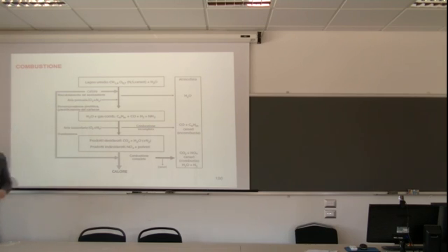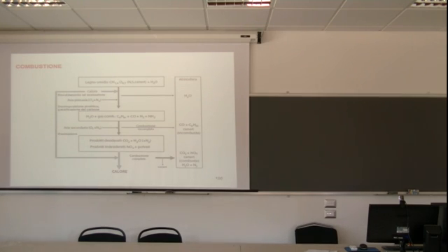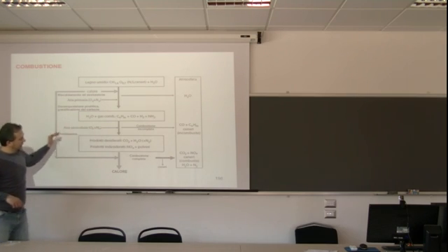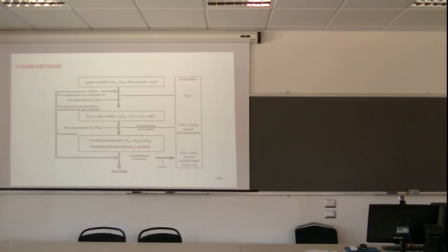Primary air is for the first part of combustion, because of course you have this process in general, but when you start with pyrolysis inside the biomass, you just have some combustion, some oxidation in the external part. So this is the primary air that you need for the external combustion. And then you have the secondary air, so some other air you need for the complete combustion of the biomass. Okay?